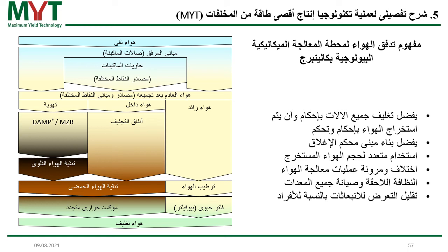And actually, we go so far that we have negative pressure in our buildings, so that the air which is polluted with odor cannot leave the buildings. Only fresh air can get into the buildings, but polluted air and emissions cannot get out of the buildings. This is why we have them with negative pressure in Germany.